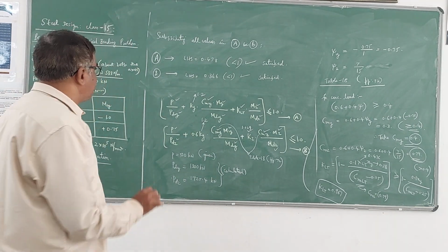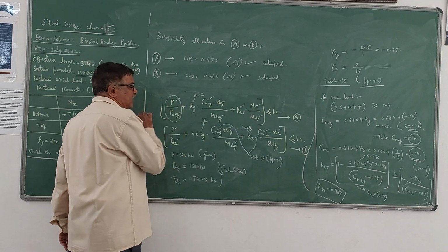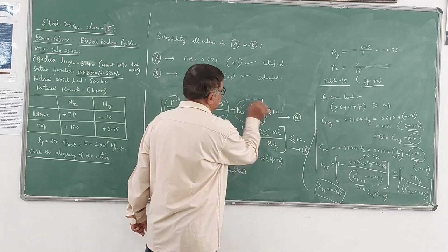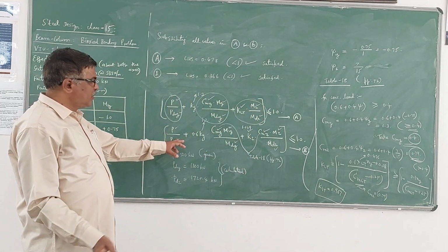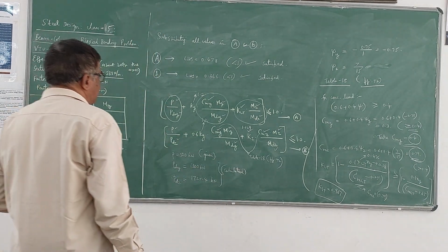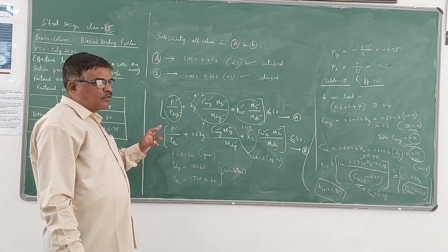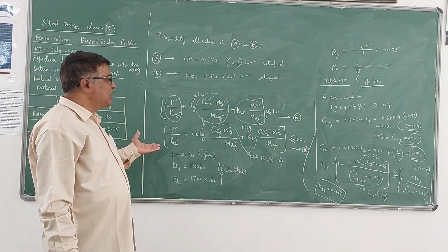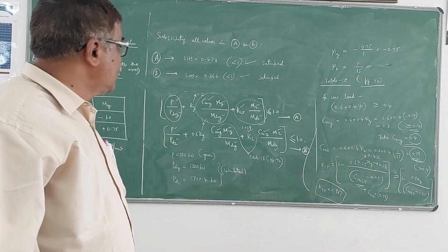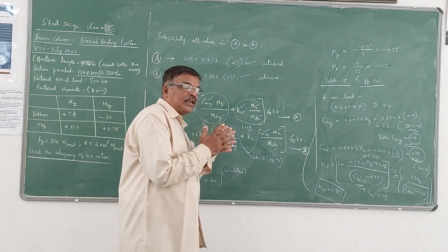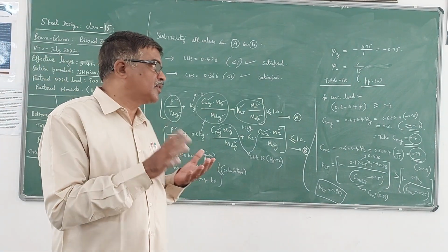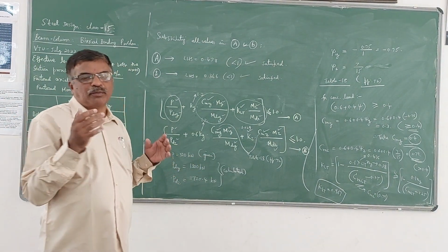Here we can see the first term represents the ratio along the axial direction, the second term along the y direction moment, the third term along the z direction moment. Since we have moment along both directions, for the biaxial case you will have two equations, whereas for the uniaxial case you have only one equation, which I explained in the earlier lecture. So this is how we check the adequacy of the given section when the beam column is subjected to axial compressive load, moment along y direction, and moment along z direction.